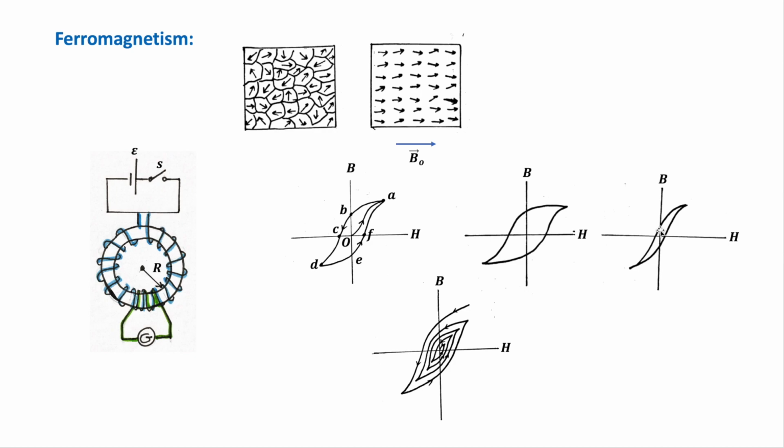To fully demagnetize a ferromagnetic material, it is taken through successive loops where the applied field is gradually decreased, as in this case. Also, another point is that the area enclosed by the magnetization curve represents the work required to take the material through the hysteresis cycle.